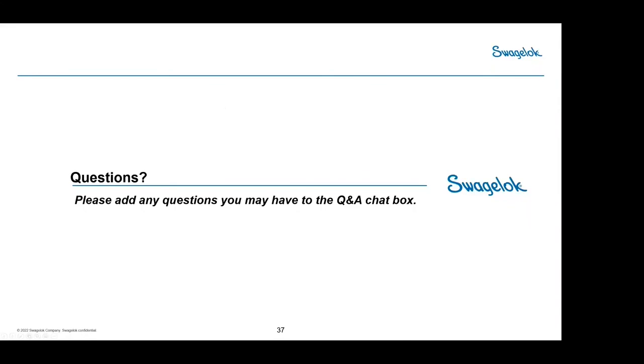Good question, John. Thank you. One of the things that I talked about earlier, and I'm not going to try to move back to that slide because it's going to give people seizure, is extremely important. You have to understand the media really well on what is going to go through that valve or fittings or any other component that you're looking at, and that media has to be very compatible with the material of construction that you're picking. So if you're picking a valve that is going to see extreme chemistries, you may have to look at things like Hastelloy or things different than your traditional stainless steel. Some of those things become very, very critical.